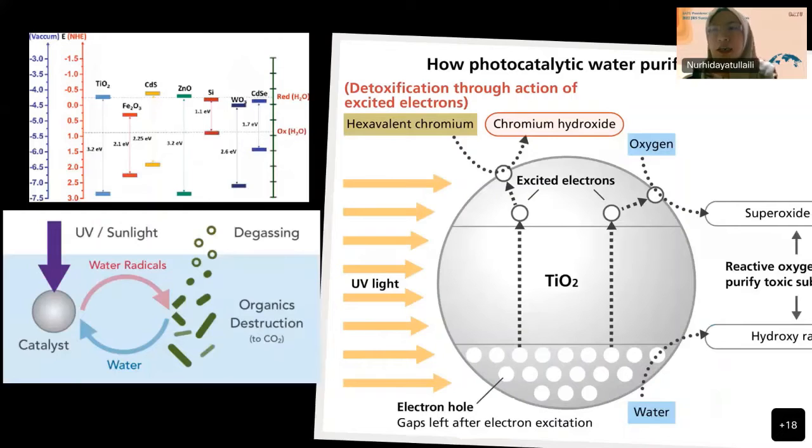Here, in the 1950s, some Japanese scientists, Fujishima and colleagues, introduced photocatalytic water purification. The basic principle is using light to activate semiconductors, normally nanoparticles. This process is considered a sustainable treatment, since it has the ability to completely mineralize the water pollutant without producing any secondary pollutants.